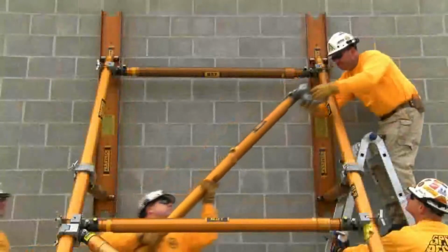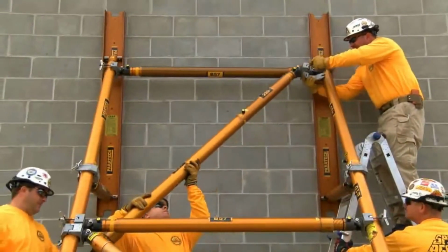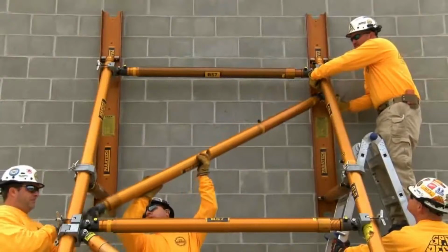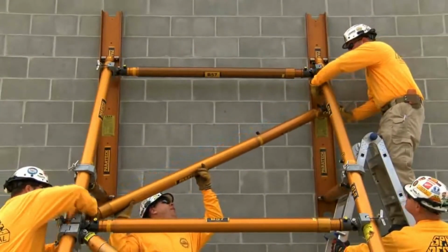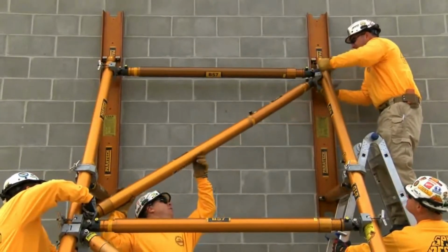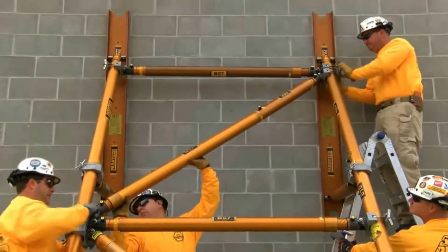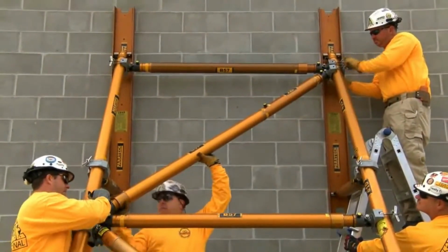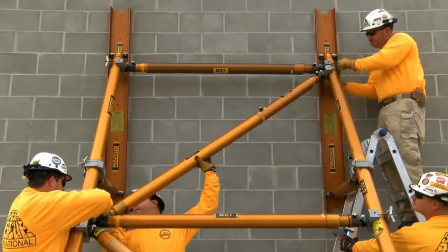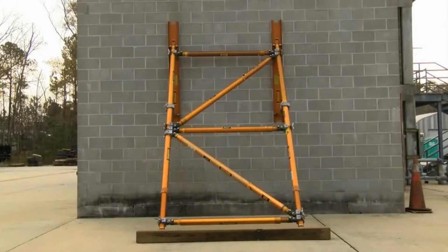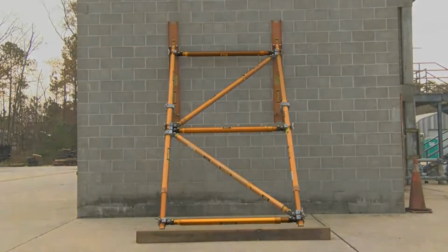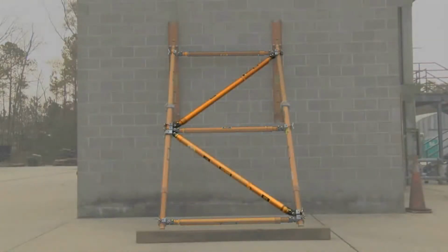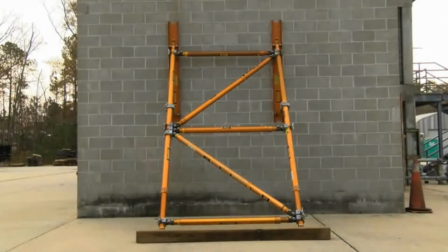Bring in the last brace to the system, which is the second diagonal. Again, attach at the top the non-movable end, non-adjustable end first. Bring the clamps and clevises up to the top right as tight as possible. Once tight, attach the clamp and clevis to the bottom. Here's the completed Paratech Absolute Raker. There are 3 lateral braces and 2 diagonal braces, which make the K brace.